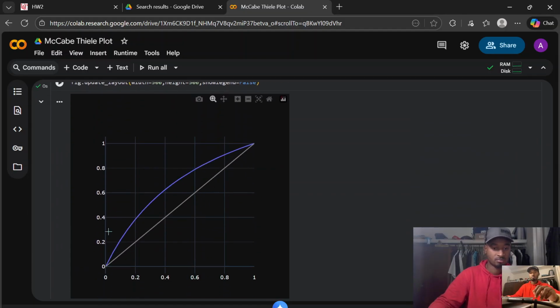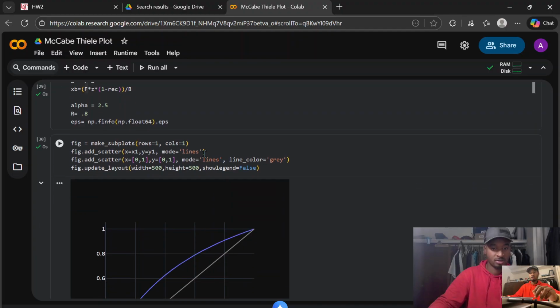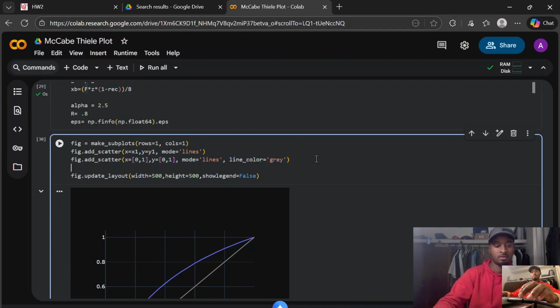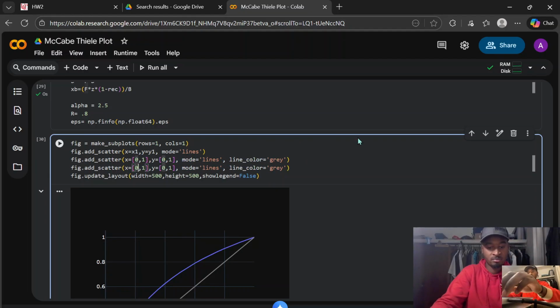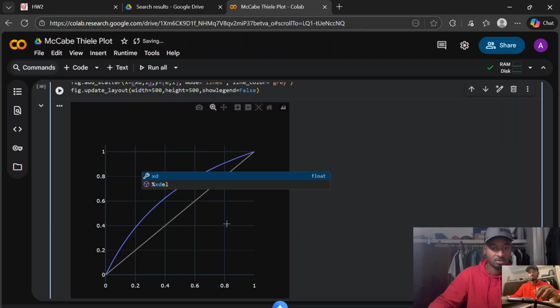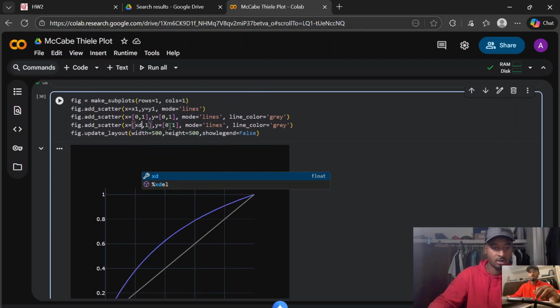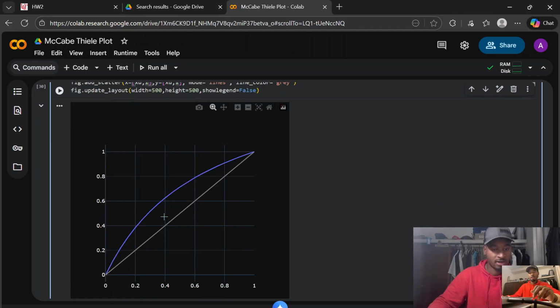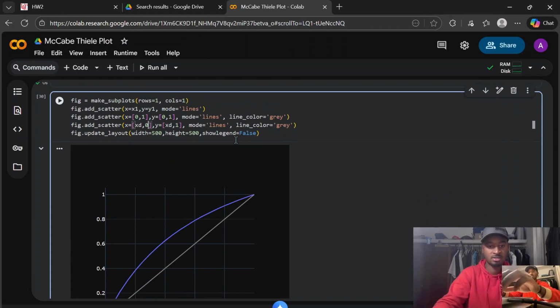We have our VLE diagram here. So now we'll start by adding in the line for the rectifying section in this diagram. So first we start at XD. So here our starting point for this line will be at XD, right? And then for Y, that starting point will be XD as well. And then here, our ending point will be when x gets to 0 here. So we'll say that x is 0.